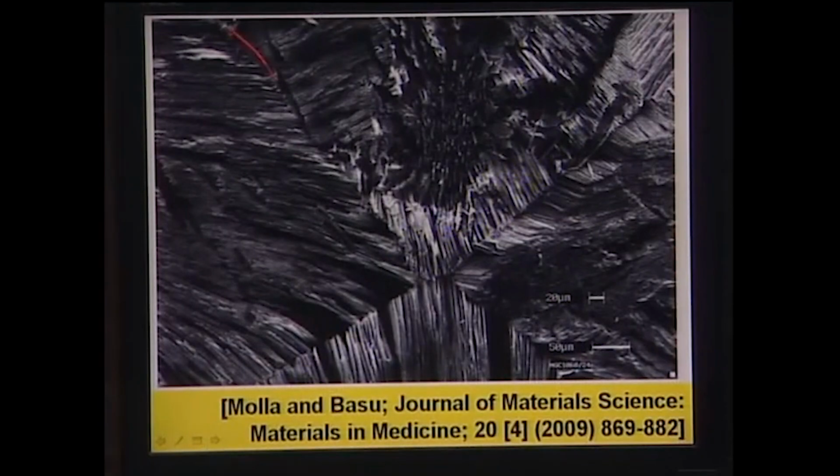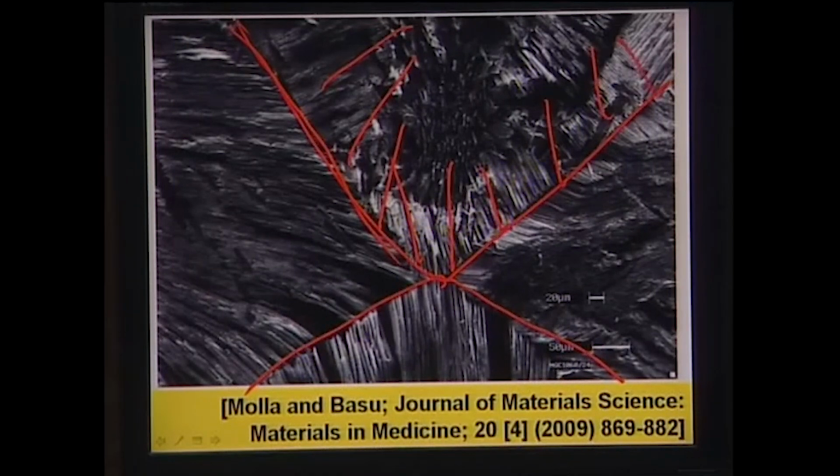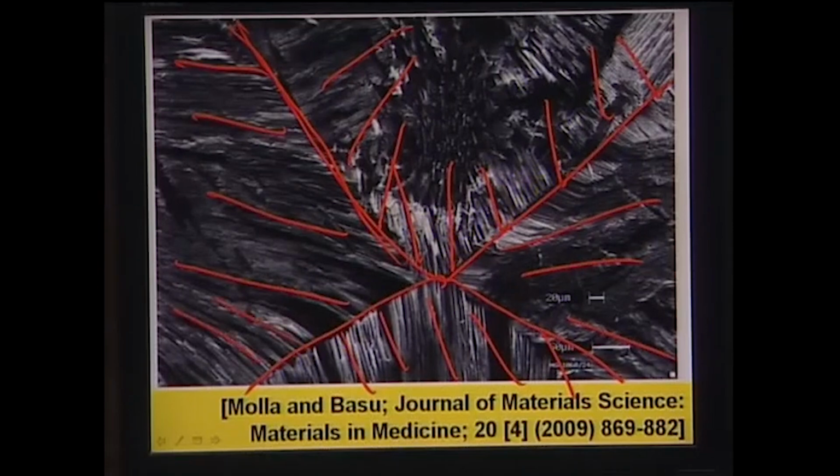More interestingly, the high magnification SEM image tells you that these glass ceramic materials have what we call envelope type of crystals. If you remember the postal envelope, it has this kind of shape, and in each individual envelope you have these glass ceramic crystals, which are oriented differently in different directions. Therefore these crystal domains meet at a particular location here, thereby forming the envelope-like crystals.